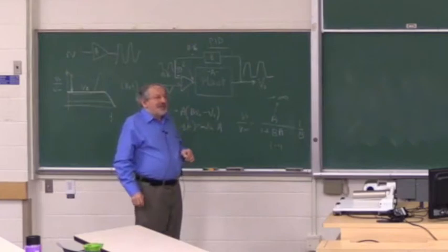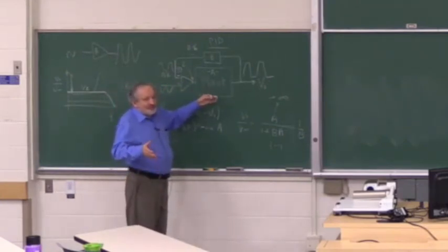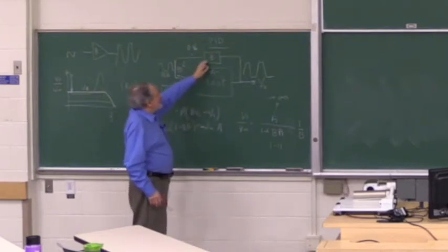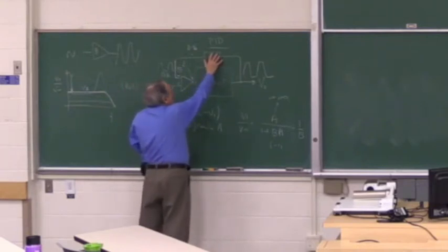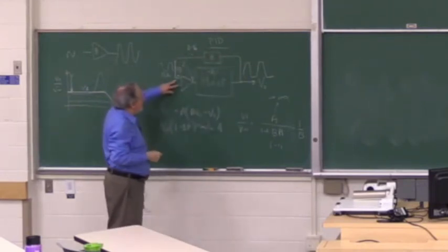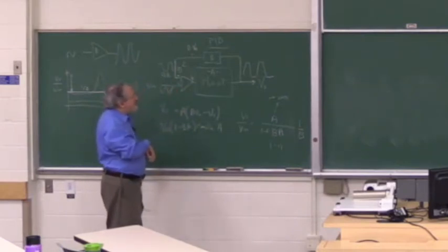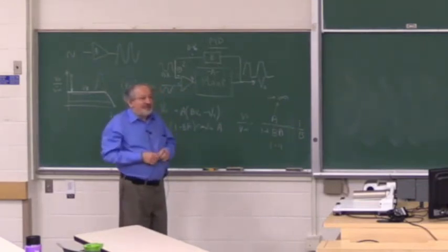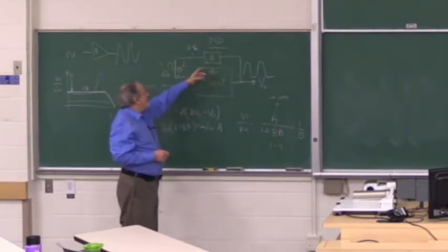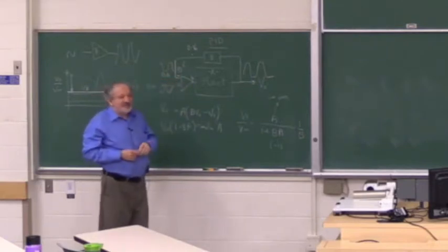Good. Now, if the gain is, let's say, more than 1, 2, 5, 10, if that phase shift is small, it wouldn't oscillate. Because if this has no phase shift at all, everything will be perfect. It will take the difference and control it perfectly. Now, if the phase shift is small, it's not going to make a big difference. Okay, it only starts becoming a problem when the phase shift becomes so big that instead of taking the difference, it takes the sum. So at what phase shift will it be the sum instead of the difference?